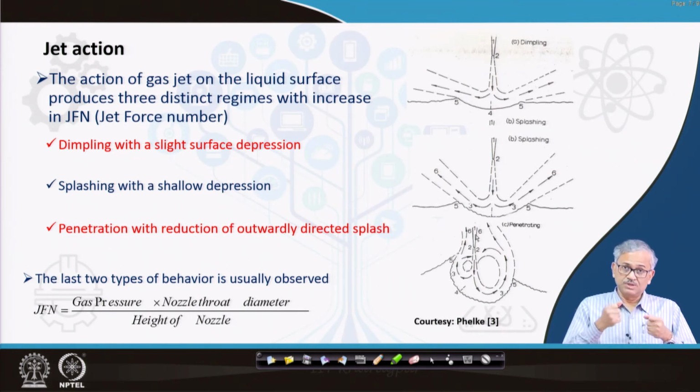So if GFN is very high and the crater is very big, in that case the rate of decarburization can be more than that of the FeO formation, and that condition gives rise to the drying of the slag, and that is called the hard blow, right? That is called a hard blow. And people sometimes do it only to increase the decarburization to a much faster rate. Okay, otherwise it is not justified. And in that case, you can blow a little softer. You can make a quite soft blow.